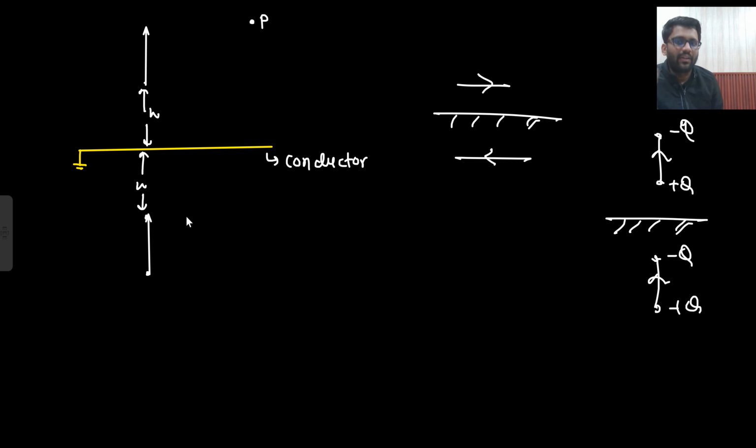So this is another antenna we are getting, but the direction of current is the same. If this has I naught current, this also has I naught current. You will never write that, sir, the current would be I naught e to the power j pi. But if this has I naught current, then how much current does this have? E to the power j pi current. Are you getting this point?